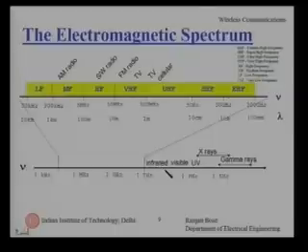The most important thing that we need to know is that different frequencies get attenuated differently by air. Okay? So, air is a frequency selective channel in the sense of attenuation. Later on, we will also see other frequency selective properties of the channel. So, for wireless communication, air is the channel. However, if we pump in say 1 milliwatt of power at 20 kilohertz, it might go to a certain distance before getting attenuated beyond the receiver sensitivity.